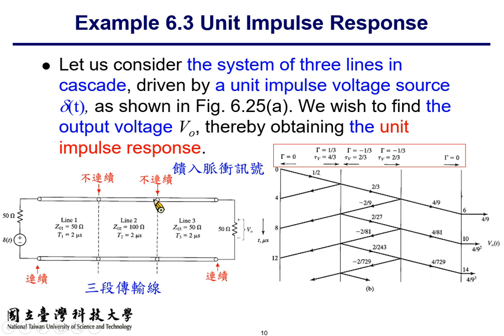And this saves us a lot of trouble, because when the signal reaches the right end, will there be any reflected signal here? No, because you have a matched impedance case: 50 ohm line terminated with 50 ohm, so no reflection. What about the energy that goes to the right? It is absorbed by this 50 ohm resistor and turned into heat.